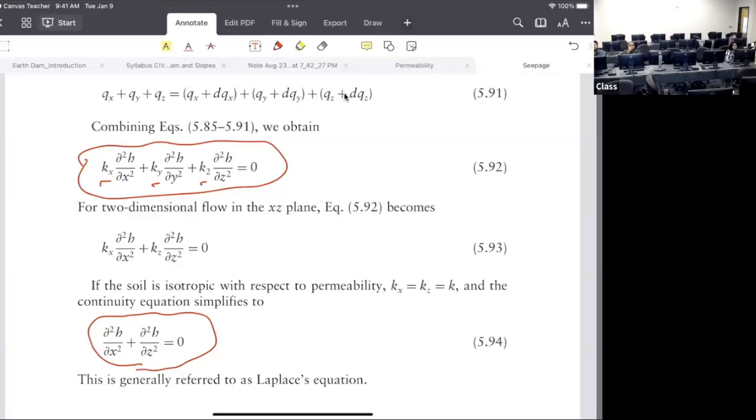Different kinds of strata. Give me an example of an earth material which is homogeneous and isotropic. Truly homogeneous and isotropic. Sea beach. Okay, so what do we have in the sea beach? Clean sand. Clean sand has a uniform distribution of the pores. So that pore space is distributed all over the place equally, right? So that's the isotropic condition, perfectly isotropic condition.